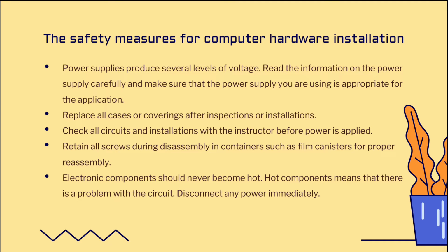Next, power supplies produce several levels of voltage. Read the information on the power supply carefully and make sure that the power supply you are using is appropriate for the application. Replace all cases or coverings after inspection or installation. Check all circuits and installation with the instructor before power is applied.